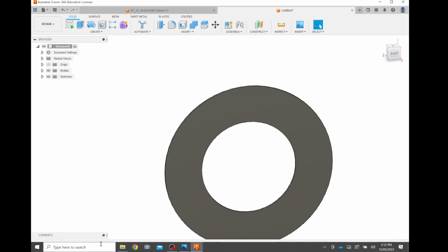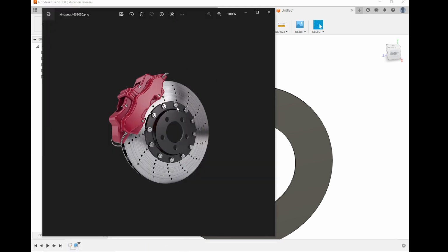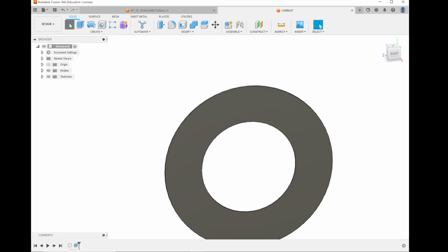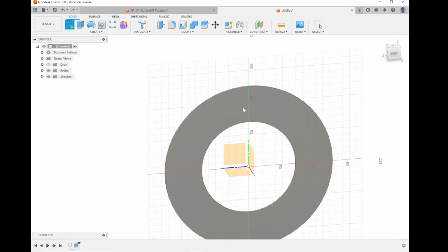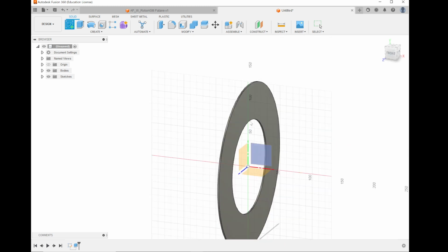Now let's be a bit fancy. We want to get these dots over here, these holes along here. We're going to start by making a sketch. Now, we can use our same sketch thing that we used before, but let's learn something new. A sketch can be started on any flat surface. It has to be flat. The angle doesn't matter, but it won't work on a curve.